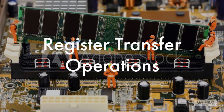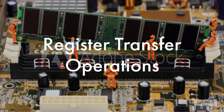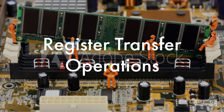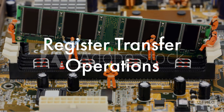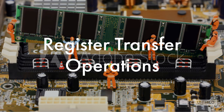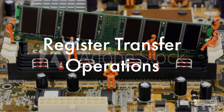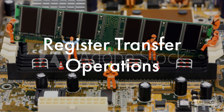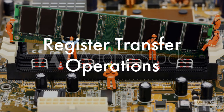Data paths are defined by their registers and the operations performed on binary data stored in the registers. Examples of register operations are load, clear, shift, and count. The movement of data stored in registers and the processing performed on the data are referred to as register transfer operations, which are specified by the following three basic components: the set of registers in the system, the operations that are performed on the data stored in the registers, and the control that supervises the sequence of operations in the system.